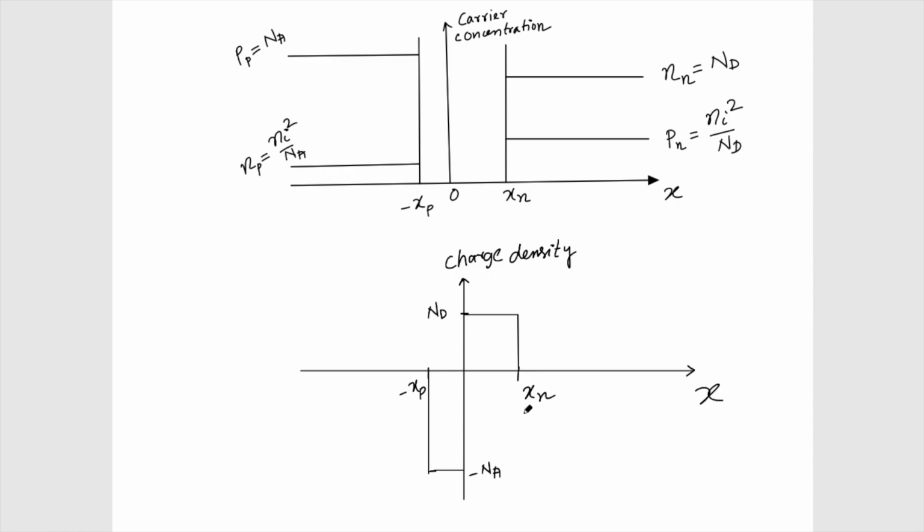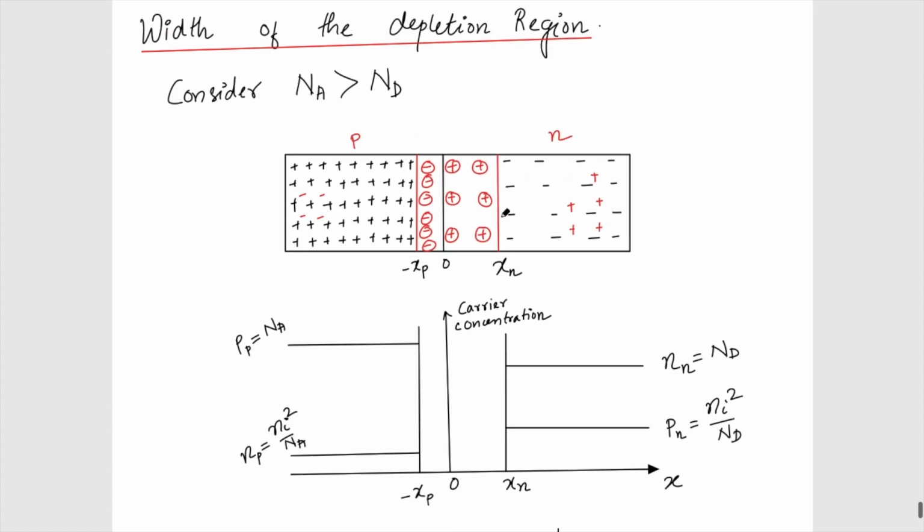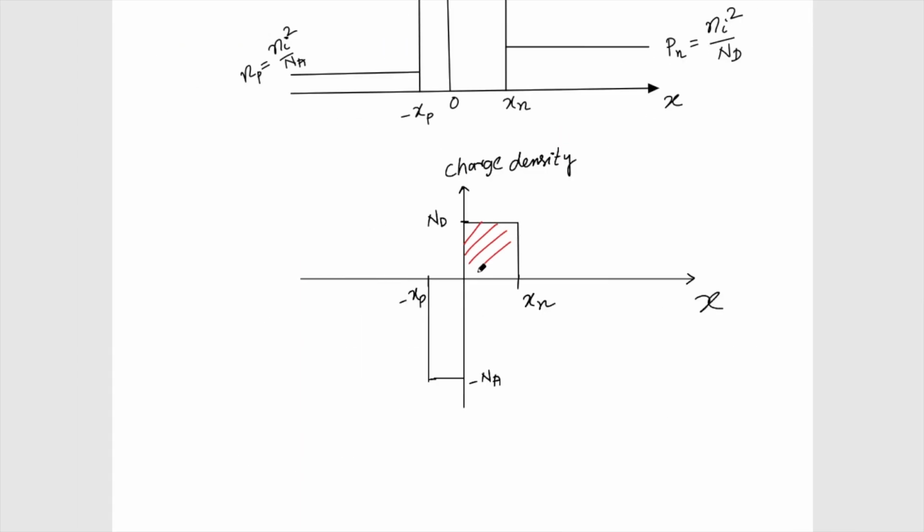Okay, so in perfect equilibrium condition, these two charge quantities are going to become the same. So the area under this multiplied by the cross section will give the total charge in this region, and similarly vice versa is true for this region as well. This area will give basically the Q plus, which is equal to the area of the cross section. A is basically the area of the cross section of this bar, this p-n junction bar,